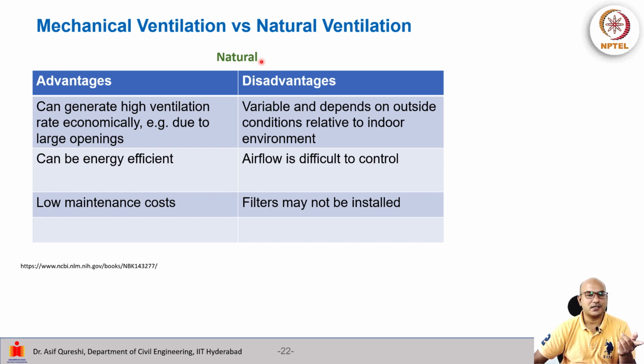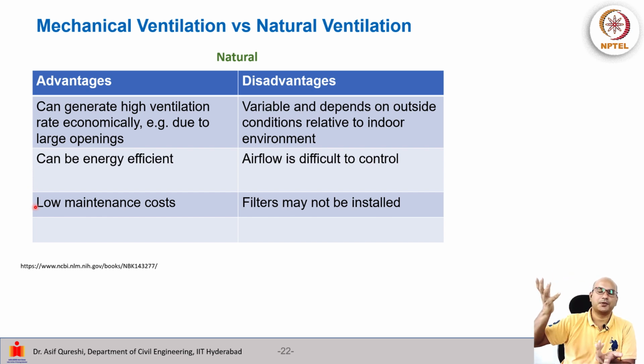Now, in contrast, in a natural ventilation mechanism, we can have a high ventilation rate generated economically, because maybe our openings are large. If we have designed it suitably, we have a large opening and air is flowing, so we are achieving a high ventilation rate without any cost. It can be energy efficient because we are not requiring any electricity. It is providing cooling or ventilation without consumption of electricity. Maintenance costs are also low because all you need is openings. Openings are not going to close down, so the maintenance costs are quite low.